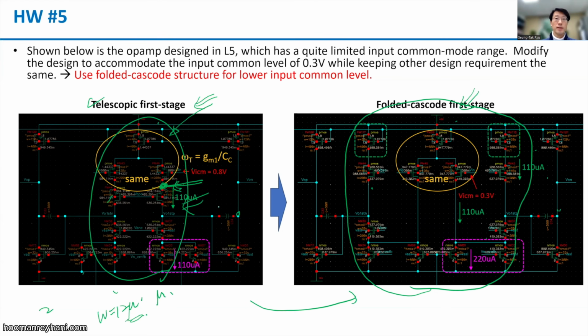One more thing is that different from the design here, where the high frequency pole can be generated here, and the second pole, of course, will be a high frequency pole. And while this is a current source, we don't have a considerable pole there because the signal doesn't go through that path. But in this case, we have a signal path like this: the output pole, which is going to be the second pole, and the non-dominant pole is made at this point, different from this point, right?